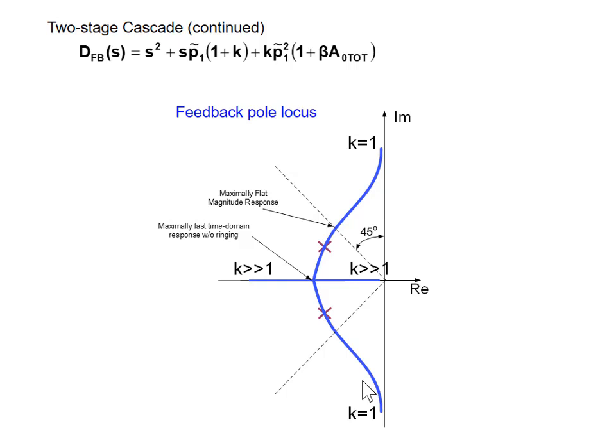here and here. The angle they make is between 45 and 90 degrees, or the poles are coincident. We typically don't like to design amplifiers so the feedback poles are out here someplace, widely separated on the negative real axis. Any idea why we don't want to do that?